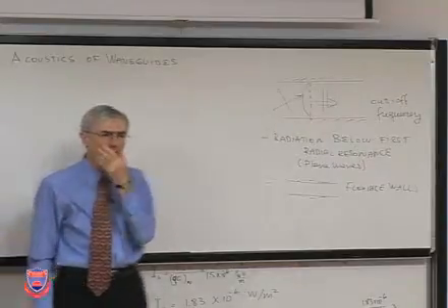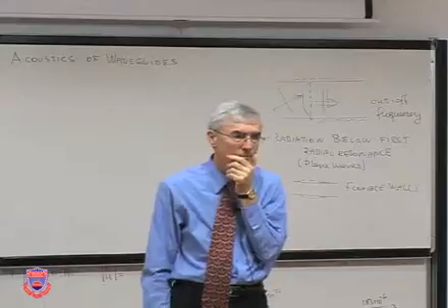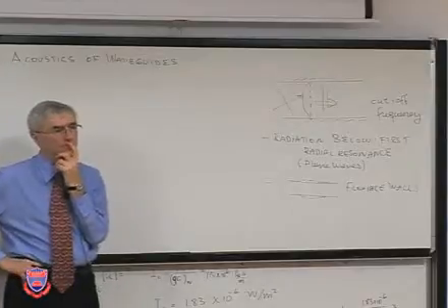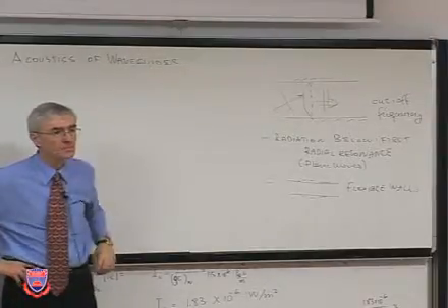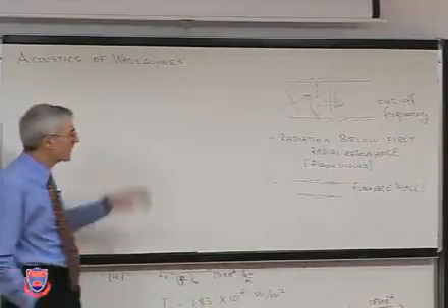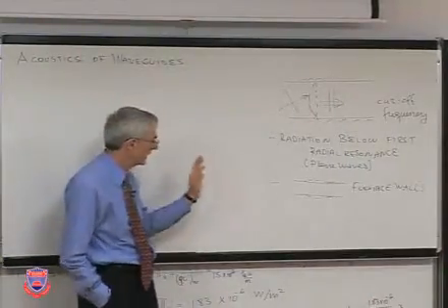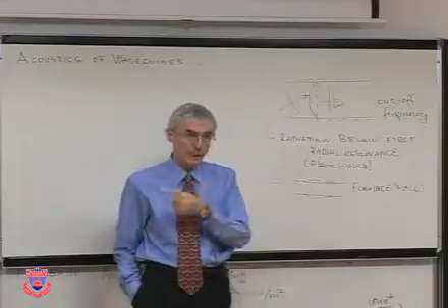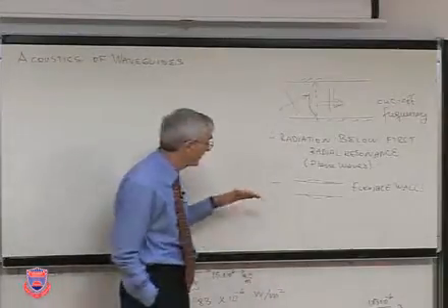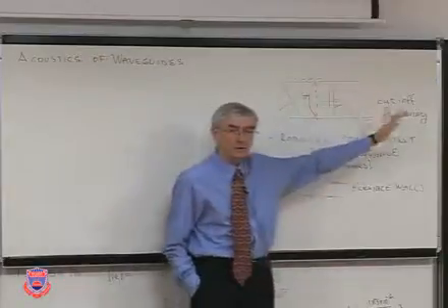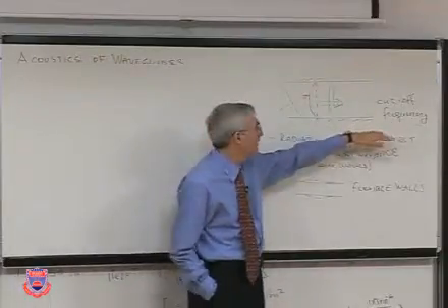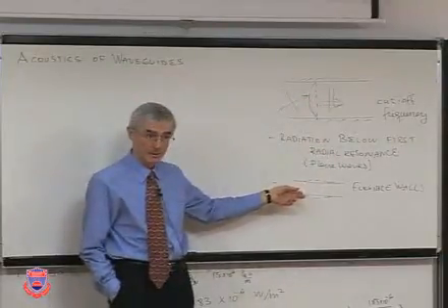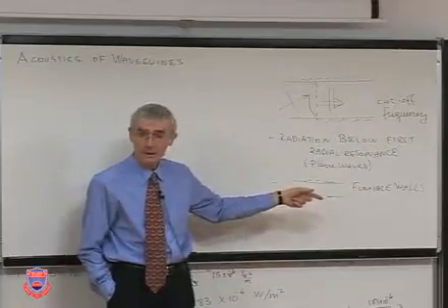You're writing that the velocity is continuous on both sides of the wall. Mm-hmm. What you should think about is that sound is a pressure wave going through. Pressure times an area is a force, okay? So as sound is traveling, a force is acting on the sides. But because these are assumed to be rigid, it makes no difference. But if they're flexible, what will happen to them? They will start flexing, okay?